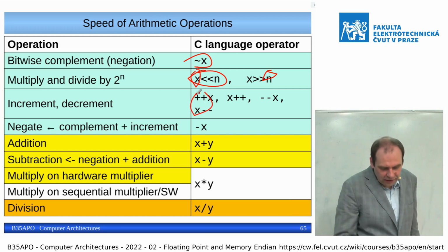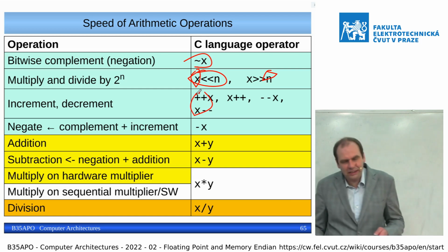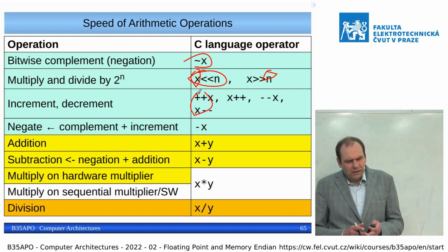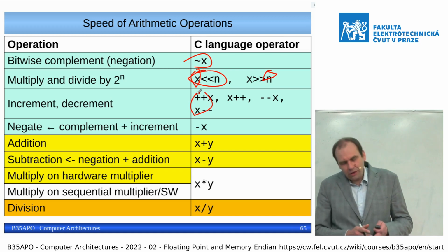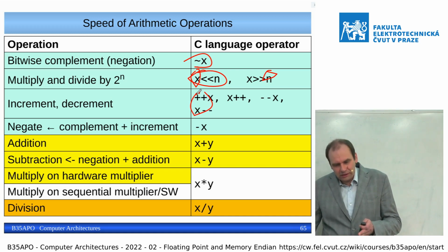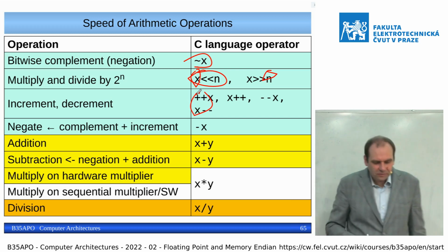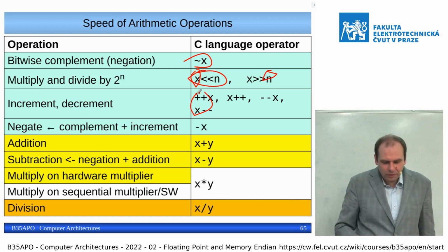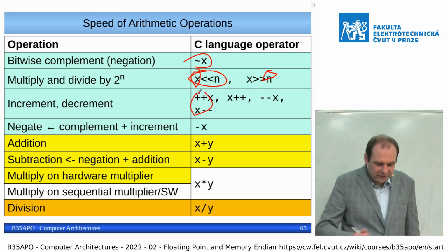Then the increment decrement, we have seen that in this case we only need to compute the logic end of the least significant bits and then flip a given bit according to at the time when all previous bits have been at 1, and there is an increment.